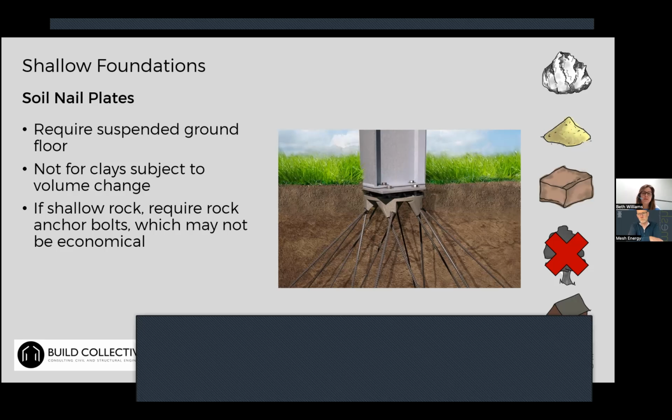If it's a domestic extension, we might take a bit more of a view on it. But the other thing to consider is if you are using piles, you need a borehole to be able to design the piles in the first place, to give you data of the ground profile that you're going to be putting your pile into. So if you're wanting to do a piled foundation, you would need a borehole investigation anyway, so it's good to get those moving early on in the project so that you minimize the risk.